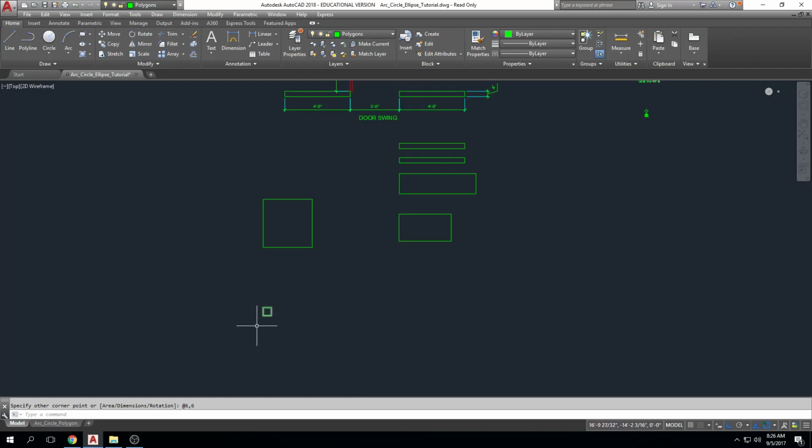And so the @ input, the relative input, really is helpful, because I can specify that first point and then say, well, I know it has to be 20 feet by 20 feet. So that's pretty helpful. I click on rectangle. First thing I could do is just do freeform, click, click. Second thing I can do is initiate it. I can click, and to specify the dimensions, I can come down here to dimensions, click, and type something like 24, 24, enter.